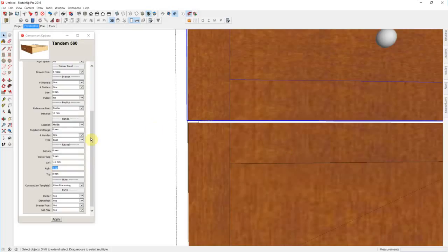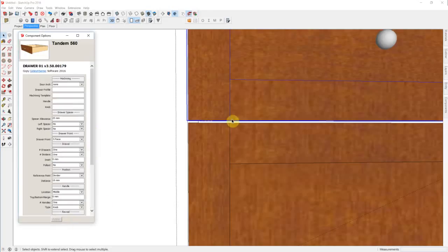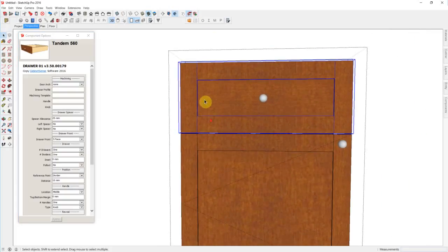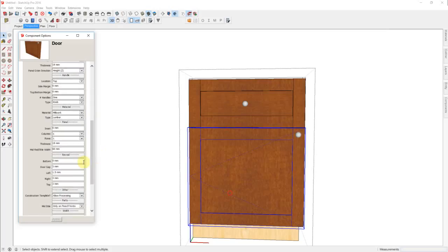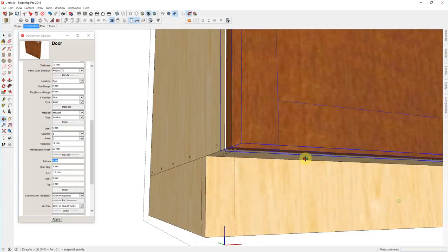but the gap is all specified on the second or on the bottom part. And I could change this and do it whichever way. I could split it in half if I wanted to. Okay, there's our 8mm on the top. Now, for our bottom, we've got the same: left 1.5mm, right 3mm. Our top is 3mm to give us the gap. And again, I've got a bottom here of 0 millimeters, meaning I'm flush to the bottom of the cabinet.